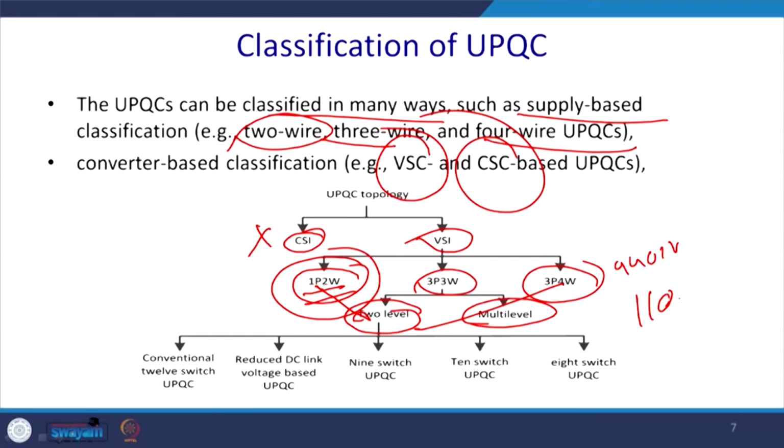So, 11 kV IGBTs, nowadays it is available, and 1100 volt IGBT. So, you will find that the voltage rating may be 10 times more, but you will find the cost is 100 times more. So, this is one of the challenges, and for this reason we try to have a multi-level inverter, so the stress across the voltage level gets reduced.